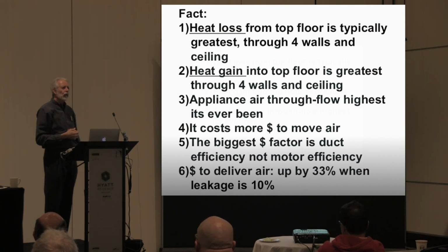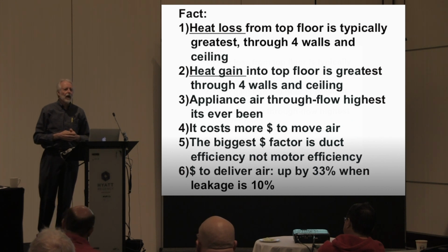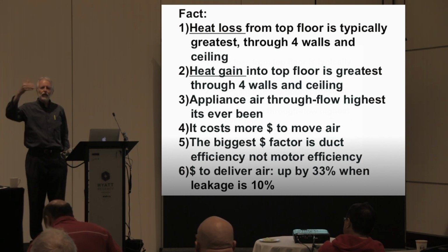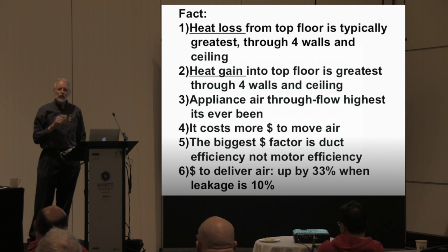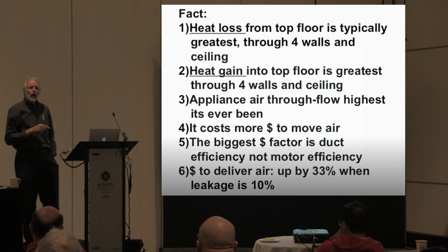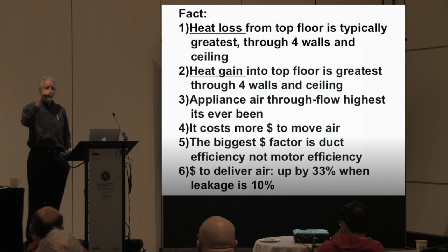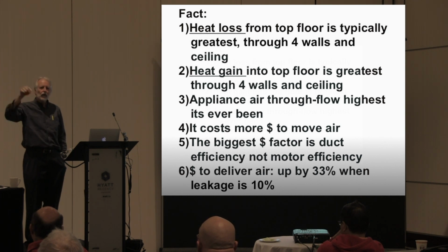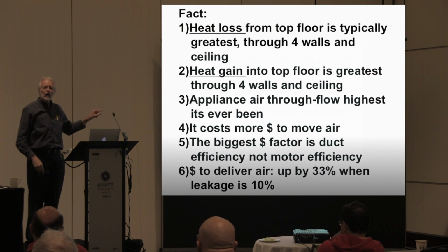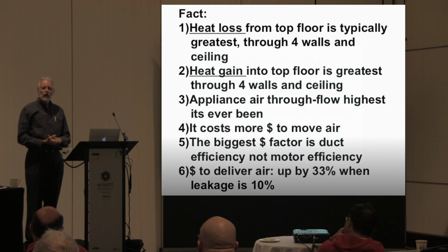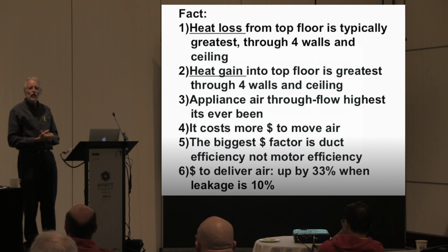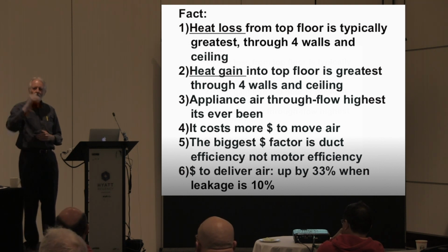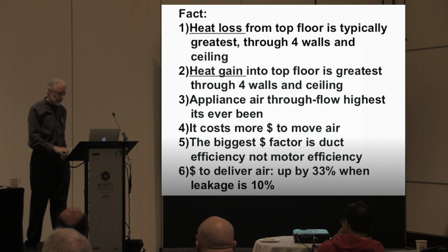Lastly, if you have duct leakage, and I'm going to spend some time on that, if you've got to deliver 50 cubic feet of air to Mrs. Smith in the bedroom to keep her cool, and your system has 10% leakage, you have to wind up that fan motor to get that same 50 to her bedroom. You're going to spend 33% more in electricity to do the job. For a 10% stinking loss of leakage, you get a big hit in the cost of moving the air to ramp up that motor to bring her back to what your design point was.